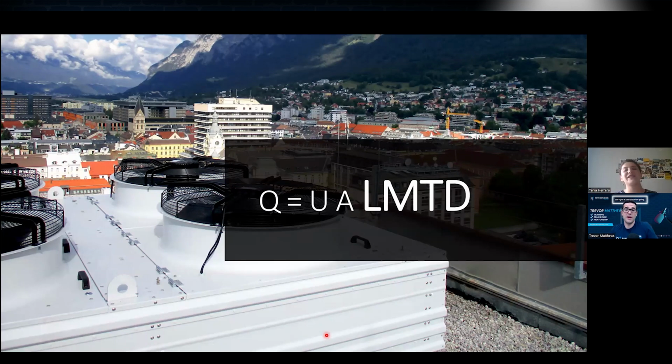So now you get that SST bigger, right? Now your compression ratio is getting bigger, more work on that. You are getting more work out of that evaporator because you're taking that SST, say, from 25 degrees Fahrenheit down to 20 degrees Fahrenheit to get a bigger TD. That's what you mean, right? To maintain the 34. Yep.